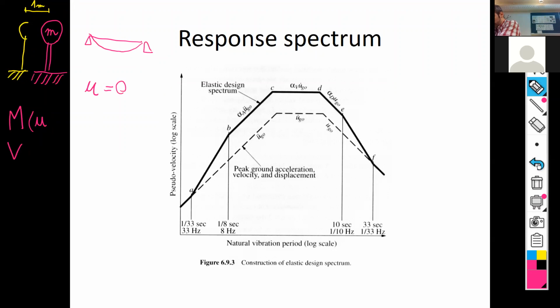But those, of course, are going to depend on the deformation, right? Maybe I could even do this. Okay, so the forces applied to our structure are the stiffness matrix of the structure times the deformation. So that's why we're interested in the deformation of the structure.